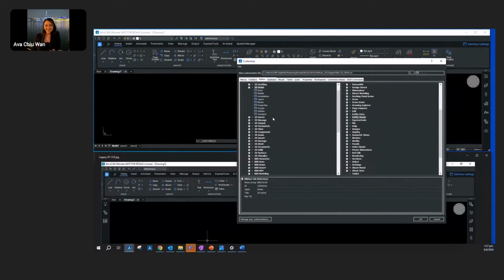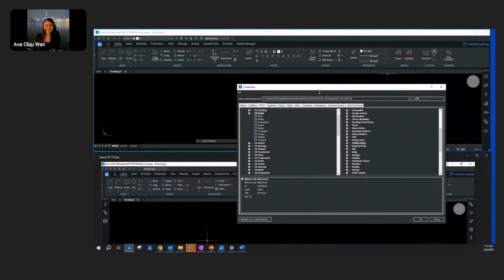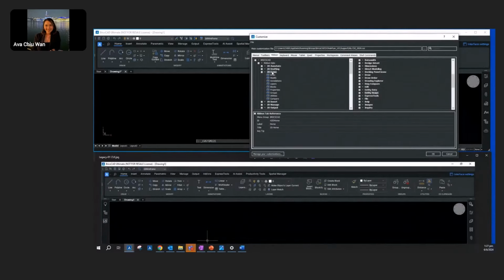So now when we start doing this, you will find that here under the home tab, we have a couple of panels over here. So when we go to the draw panel, let's double click that. You can either double click it or right click to show panel. You will see that you are again redirected to a different set of list, which is under the ribbon panel. So first things first, each panel, the first thing you will have is a row. Because if you don't have the row, you won't be able to bring in certain tools or commands, which I will show you later on.